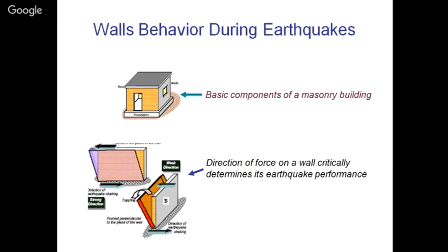But even if we are using masonry, if we provide proper connections to our structural elements, whether parallel or perpendicular to the earthquake force, and with the horizontal diaphragm level, that is, connections in plane with the cross wall and between the walls and the slab, then we are safeguarding our masonry structure from a future collapse due to earthquake.